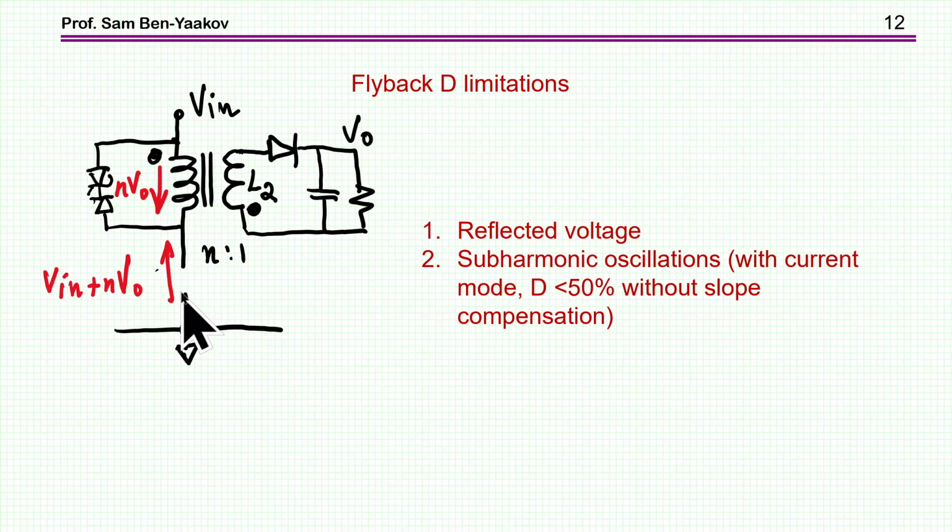When the transistor is off or disconnected, we see at the primary the voltage of the secondary reflected through this coupled inductor, and in this ratio it will be times N, so that the total voltage on the transistor is Vin, first of all, plus this reflected voltage. So when the duty cycle is small, N must be large for the same transfer ratio of the voltages, and then you might have a problem. So this is something to take into account. And then, of course, the question of subharmonic oscillation, which I've mentioned. And again, this is an additional problem that one has to be concerned about.